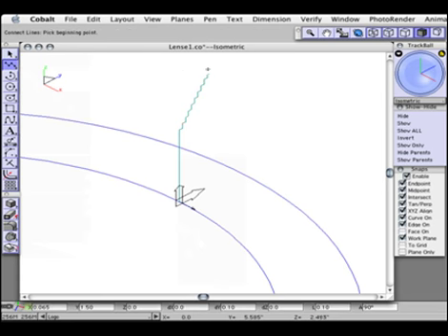Back to the connected line tool, I'm going to click and drag again, a value of 0.3, come back down, click and drag, click, and then type in a value of 0.6, hit enter. And then I'm going to start the tool again, come back down to the beginning, click to the end point, click back up, type in a value of 1.5, and then just use the drafting assistant to snap to that line we created before.